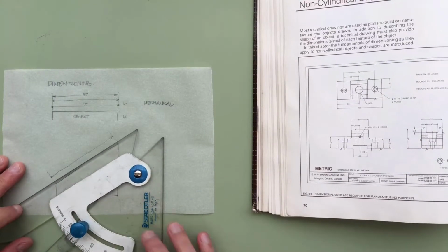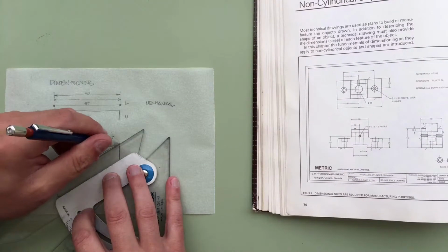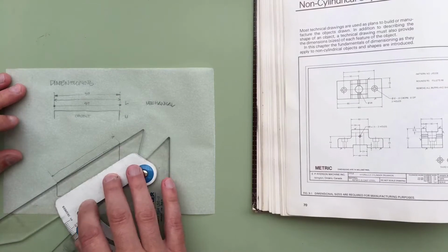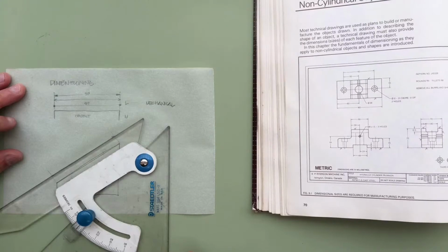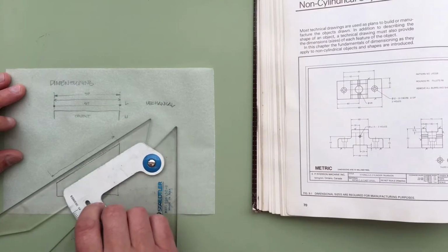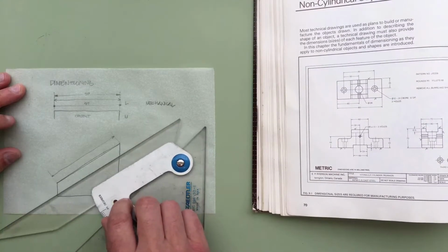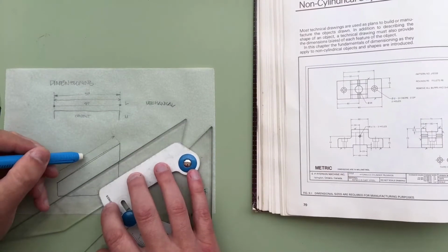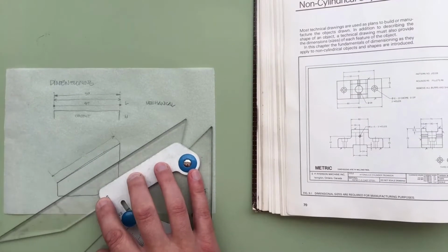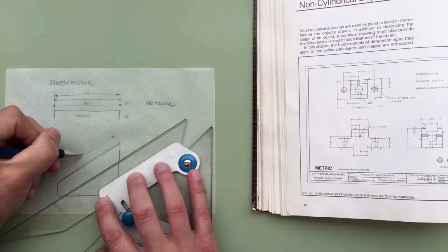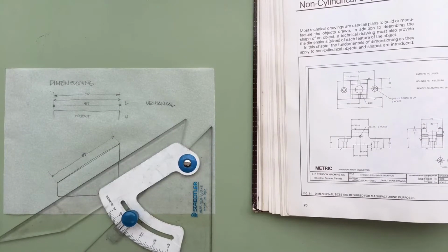When you're drawing the original line, you might use your set square to draw that line. Then when you come back to do the dimensioning, it's just a matter of either pushing your ruler up to get that lighter line placed, or you can also move the set square from side to side, so you can draw this line and then move the set square over and draw the next line. Once that's been done, I would probably avoid drawing the whole line and then erasing a piece out of the middle of it to get the text in there, and then we can get that piece of text in there. So that's something that's along an angle.